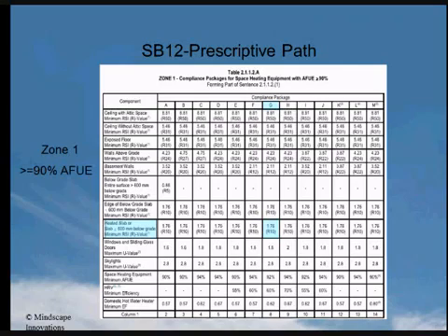For a window-to-wall ratio of 17% and below, package G requires a metric U value of 1.8 or lower, or a minimum energy rating of 21. For a window-to-wall ratio between 17 and 22%, the minimum metric U value requirement goes to a 1.6 or lower, or an energy rating of 25. Energy ratings can be found in Table 2.1.1.8. Skylights must all meet a metric U value of 2.8 or lower. There is no energy rating alternative for skylights.